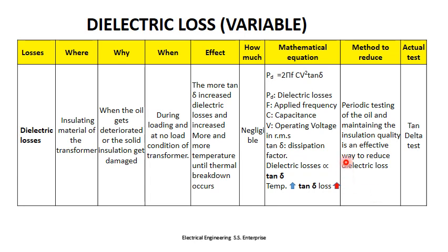How to reduce this dielectric loss? Periodic testing of the oil and maintaining the insulation quality is an effective way to reduce dielectric loss. By using the tan delta test method, we can find out these losses.